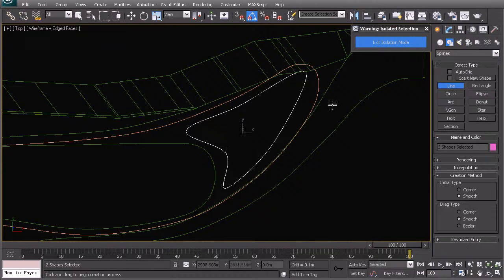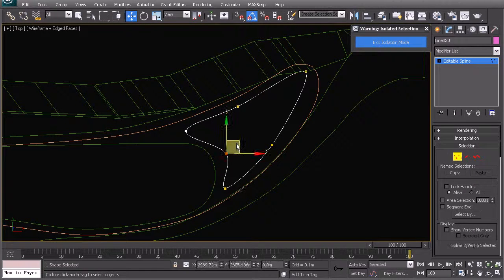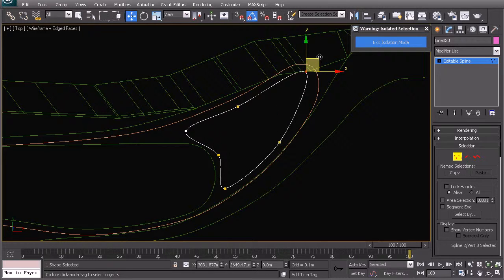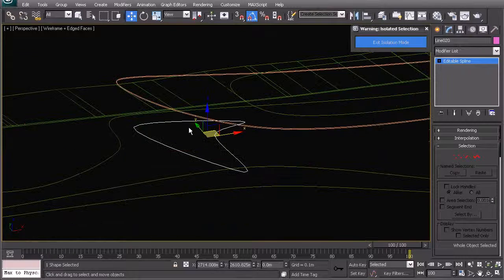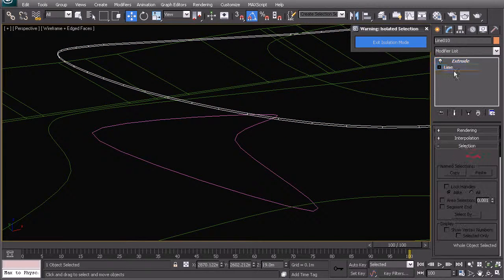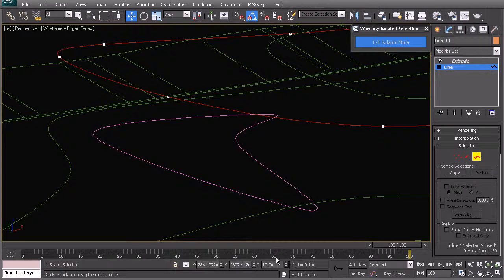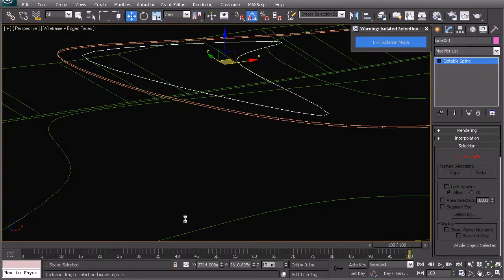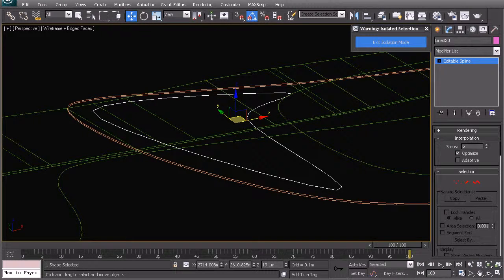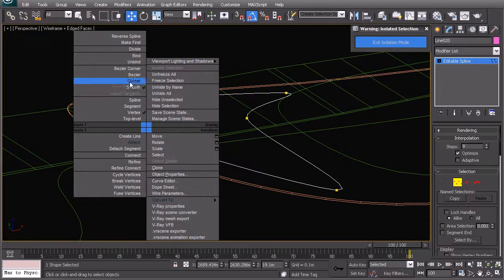And always with these splines, remember the fewer points you have, the better. Let's make this one a Bezier and stretch it out a little bit. Great, so now that you have that, you can go into your perspective view, and we just need to find out how high this slab is. We can look here that it's 19 meters. So let's go ahead and move this up till 19.1, just so that it's sitting slightly above. That is smooth.